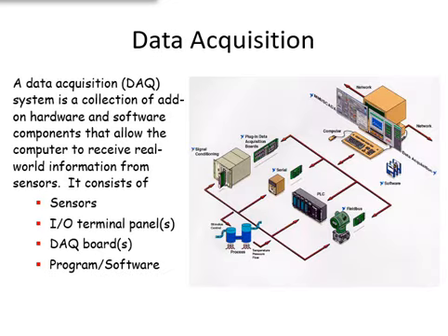As an introduction, data acquisition is the process of sampling signals that measure real-world physical conditions and converting the resulting samples into digital values that can be manipulated by a computer. Or in a simpler definition, DAQ typically converts analog waveforms into digital values for processing.